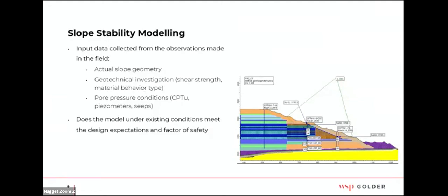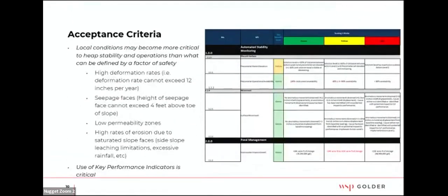And so then you can take that and use that model to develop thresholds for pore pressure within your heap, with assigning maximum pore pressure measurements in your piezometers. And then you can adjust your operation of the leach pad so that you don't exceed your factors of safety. But with that, you'll find out that heaps tend to behave anomalously at a very small scale, where even your cross sections that you set as critical sections for slope stability may not be in the right place.